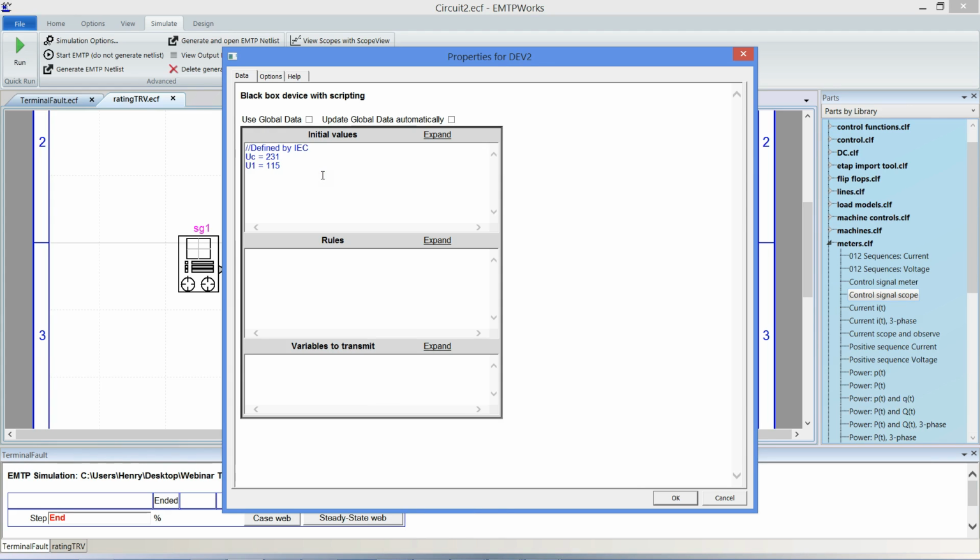Okay, T1 is 38. As a commentary I can say it's microsecond. Here it's kilovolts. Kilovolt line to ground. Then T2 it's 228 microsecond. TD it's 5 microseconds, so it's very small, 5 microsecond. So that means the time step has to be smaller than 5 microsecond at least.